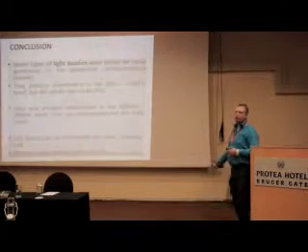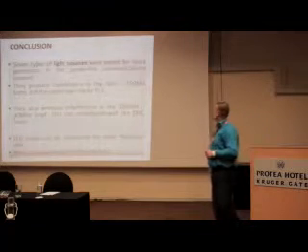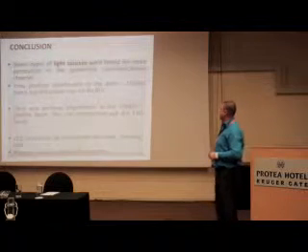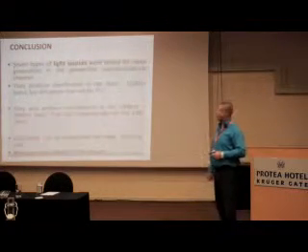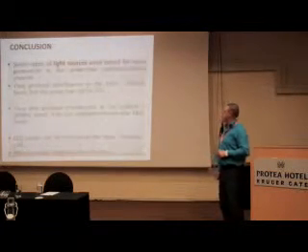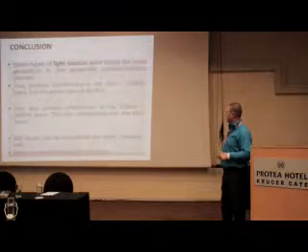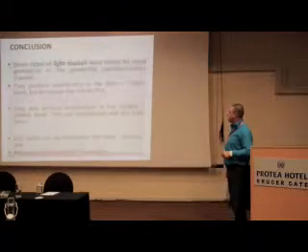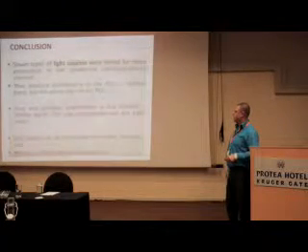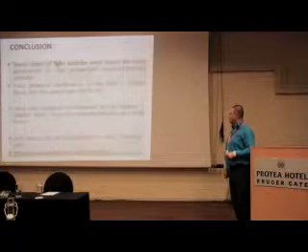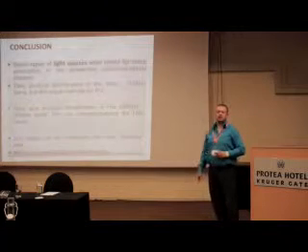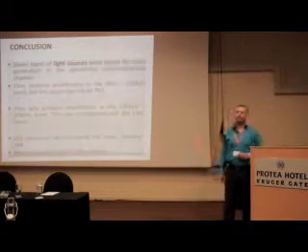And we conclude that 7 types of LED lights were tested for noise generation in the power line channel, and they produce interference in the narrowband channel, but this poses low risk or no risk sometimes to the PLC channel. They also produce interference in the high band, which sometimes competes with or exceeds the EMC levels. LED lamps can be considered the most friendly, and mercury vapor lamps are the noisiest. This is because mercury vapor lamps are the only ones that produce radiated signal as well, not just conducted signal. Thank you.